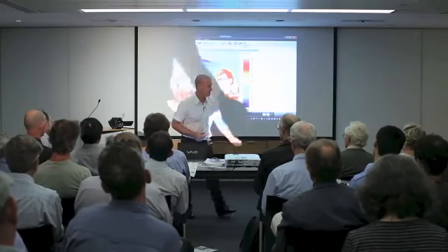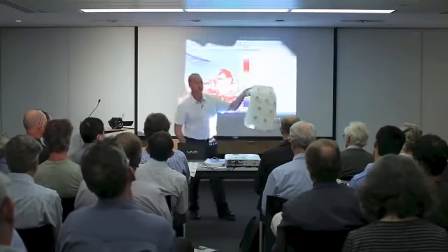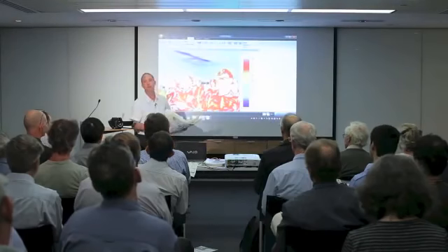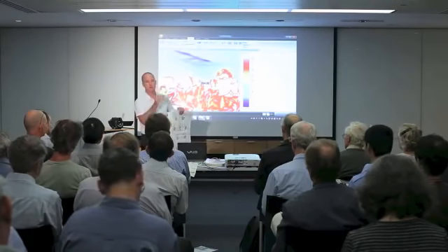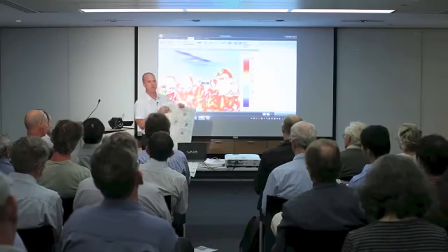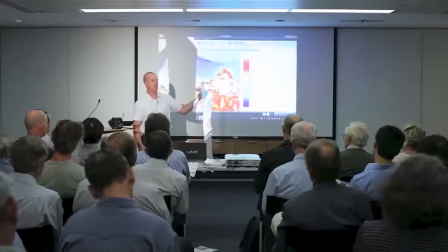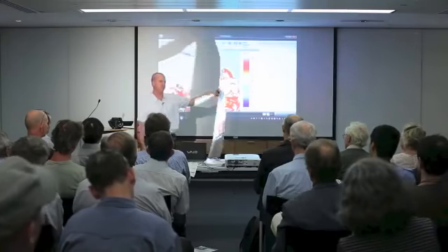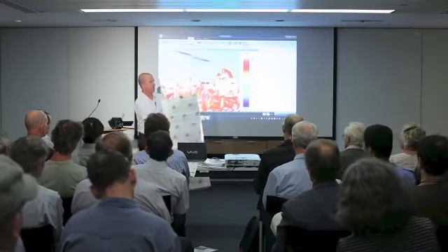The difference with that and phase change material, any kind of phase change material, is it doesn't exhibit any thermal mass property below its melt point. So below 18 degrees, this is just like a lightweight piece of plastic with some vegetable fat inside it, which is what the material is made of. So that there is just like putting a piece of concrete this thick inside your house. The difference is that once it starts to melt, it exhibits a huge thermal mass. It's about 40 times more than concrete per gram. Okay, so that's how much more energy it stores than concrete.